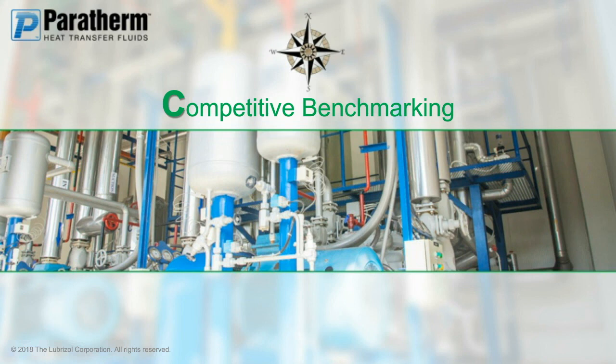So for competitive benchmarking, final product compositions vary significantly depending on the intended outcome. True thermal fluid manufacturers, true experts in this field, have the ability to engineer fluids to balance the primary factors, such as their stock ratios that they use, to give you an ideal ratio of physical properties, density, viscosity, etc. The level of process refinement: is the product hydrogenated? Is there hydrotreating? It's a purity consideration. And is there the ability to add formulation of additive packages? That's really a design functionality consideration.